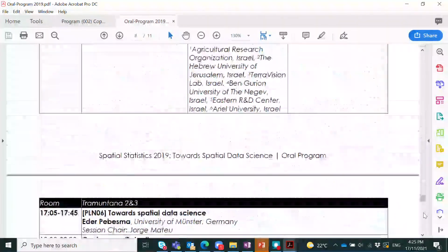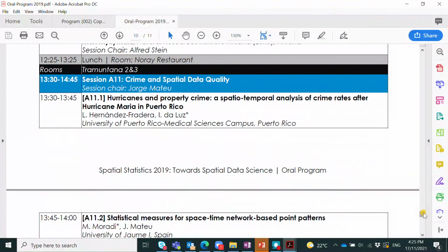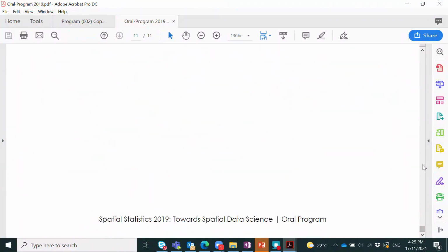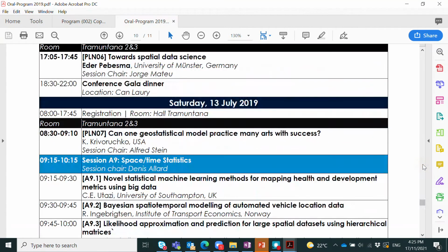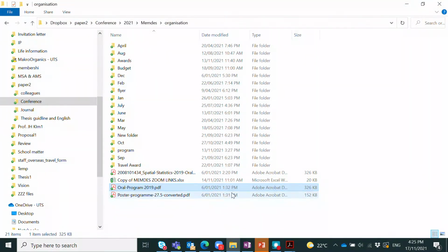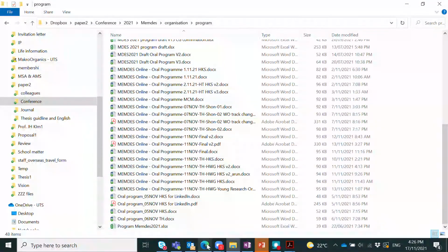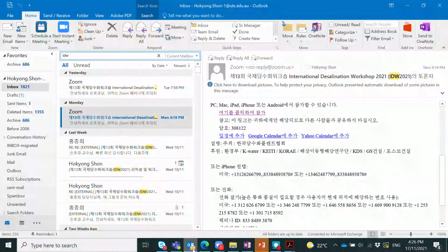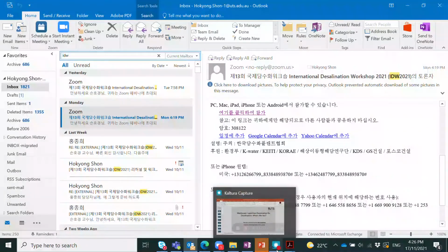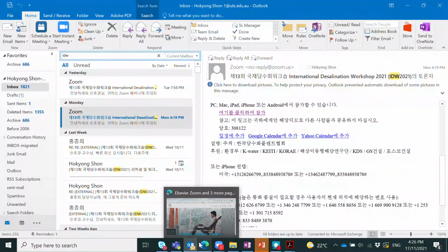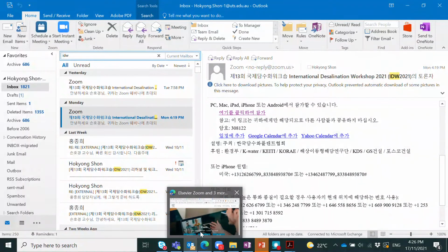The third part is about the strategies for scale control, and there are many different strategies at each step. If you imagine the steps of scale formation, initially we start with a supersaturated solution, and nucleation and crystal growth happen. Once crystallization happens, it may deposit, form a cake layer, or form surface crystals, and so flux decline happens.